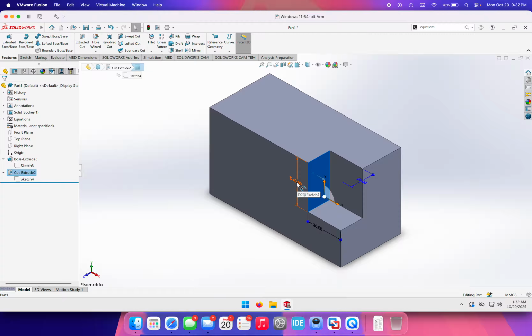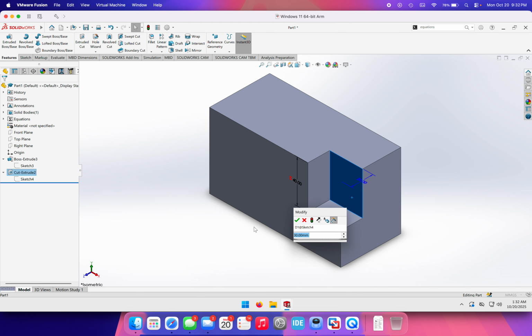And you don't have to do that within the variable itself. If you had multiple cutout heights and you had just 15 millimeters and you wanted duplicates, or maybe, actually I've got an idea, maybe you want the length of the cutout to be twice as much as the height of the cutout. You can double click on this.